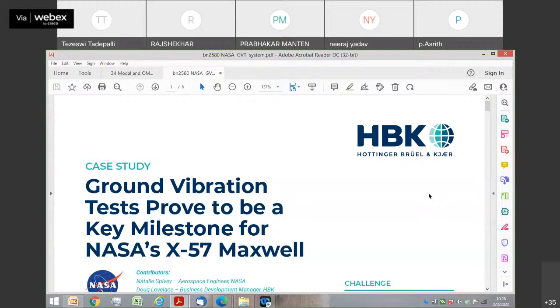Second, as I showed you in one of the examples, your data acquisition system has to have a very, very wide range, so that right from a very simple seismic to the shock, the data acquisition system is able to pick it up instantaneously without auto ranging. These are two important things: data acquisition capable of measuring the shock.